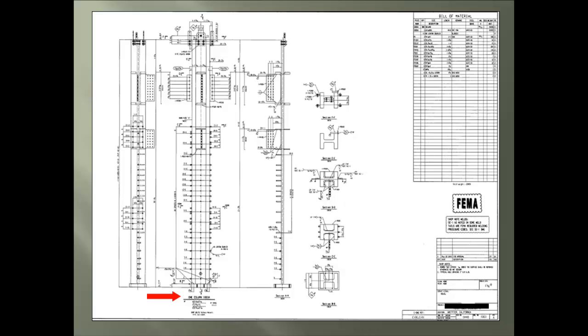The arrow points to the column call out. Here we see there is only one column for this sheet, even though it seems like there are three, but we will break all that down in a minute. Next, the piece number is shown also, and that should match the number back on the plan view sheet. If not, there must be some investigation prior to production of the column.